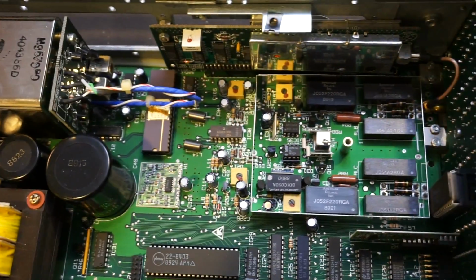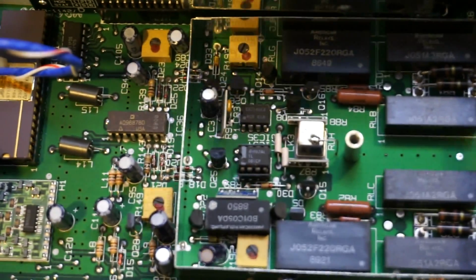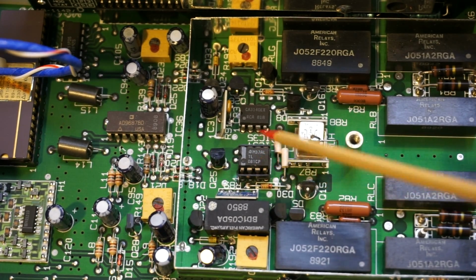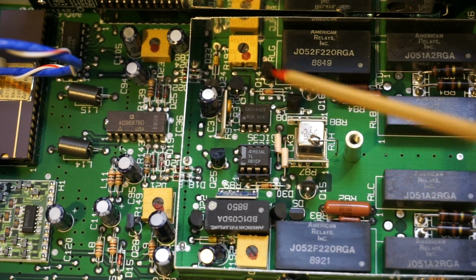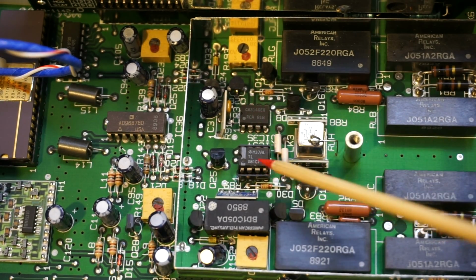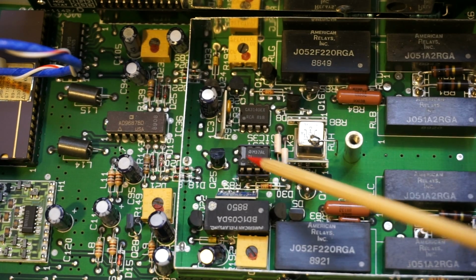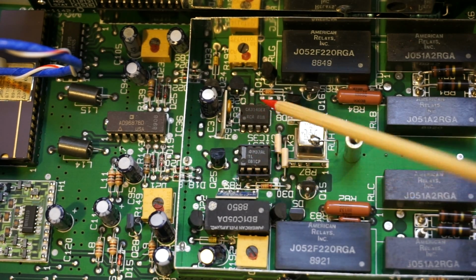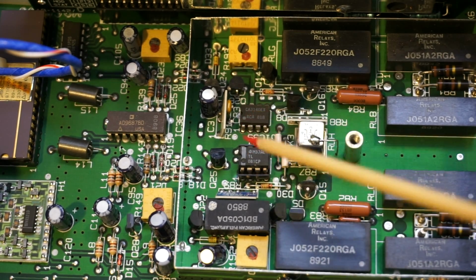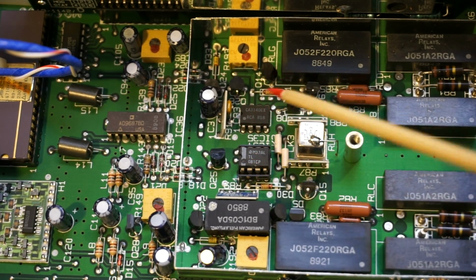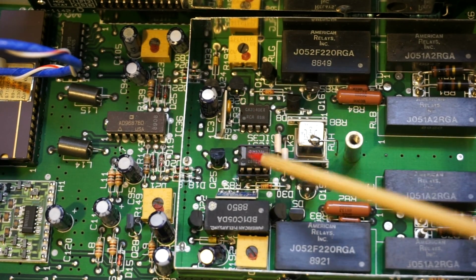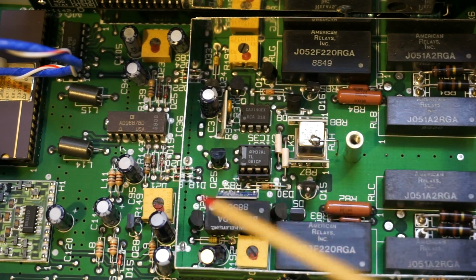So there, this is my replacement IC, and I put it in the socket. Now I don't have a CA3140 on hand, but I have plenty of TL081s. So these two are actually pretty comparable. The bandwidth gain for the TL081 is slightly lower than the CA3140, but in terms of the other parameters, they are pretty comparable.